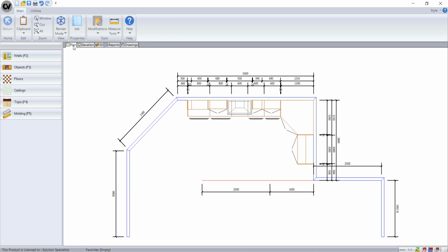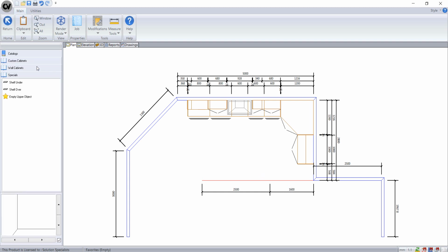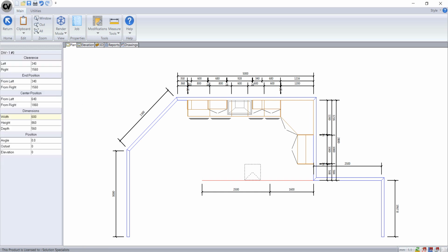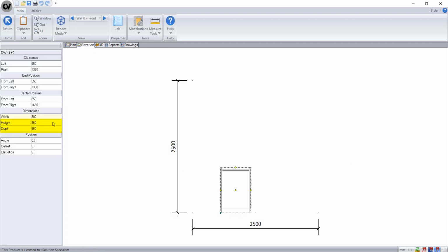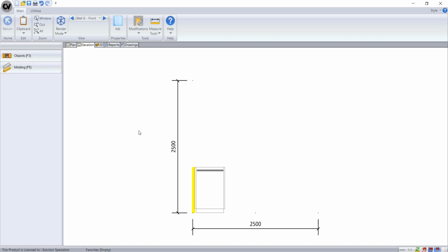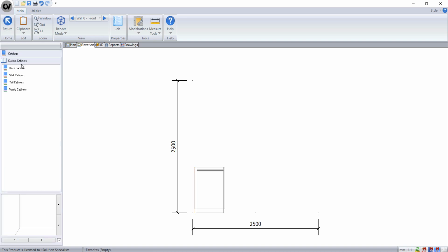With the wall cabinets complete, I'll move on to the island bench. You can position and modify objects on the peninsula wall using the same methods just shown. A dishwasher from the appliance catalogue should be placed and adjusted in size to match our base cabinets, which assists the auto-build countertop feature I will use shortly. It can be positioned from the end of the wall to allow enough space for a waterfall end to match the benchtop thickness.